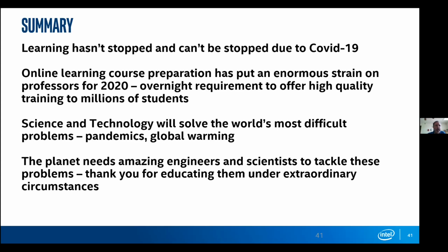There's a question about real-time digital signal processing or control. In terms of coursework, the best way to go about that is probably to go to MATLAB and look at what they have. We have a product that we call DSP Builder, which is an interface between MATLAB and mapping that into RTL and then compiled down to an FPGA. So I would use the MATLAB training, and then there's some tutorial information on how to use DSP Builder. It'll take your MATLAB description, map it to the DSP functions within the FPGA, and then you can run your experiment on a hardware accelerator.